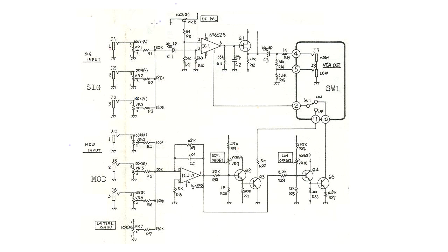And if you're wondering about this trim pot up here, especially because it's going into this 1 mega ohm resistor, forming kind of a big voltage divider with this 560 ohm resistor, this is basically here to deal with non-ideal characteristics in this real OTA. So this is putting a very, very tiny voltage here that one can use to adjust for these non-ideal effects.